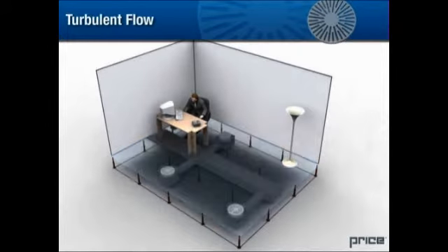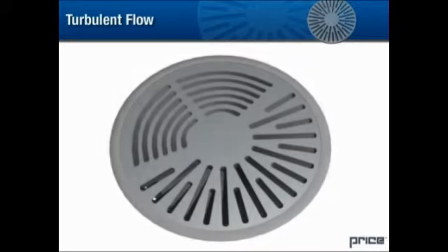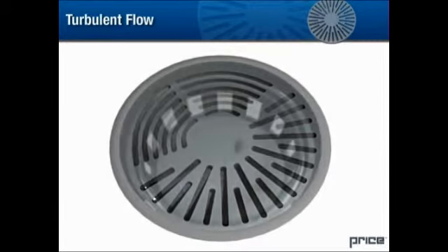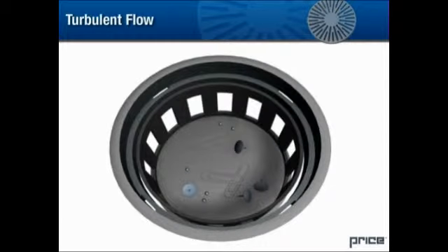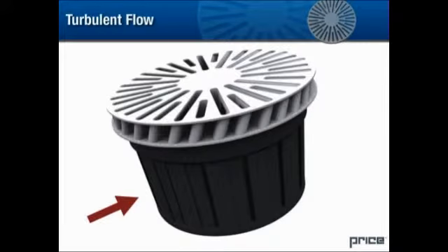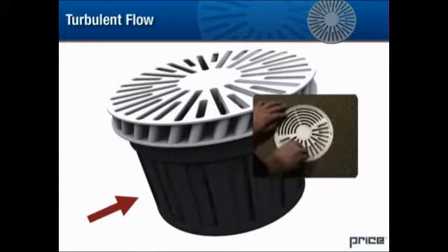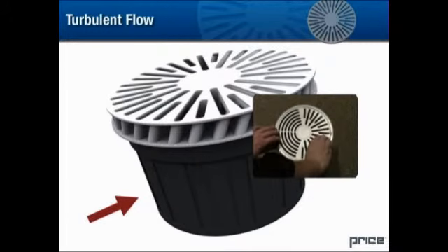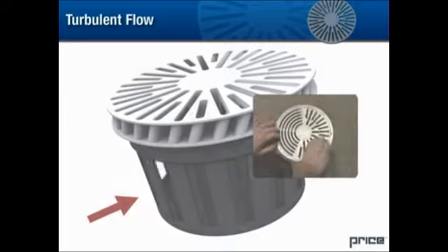The floor swirl outlet is normally inserted in the floor tiles of the conventional raised floor system. A distributor basket may be inserted under the air outlet to trap solid objects such as coins and paper clips that may fall into the air outlets. In addition, some diffusers allow the volume and direction of the local air supply to be controlled by the occupant, allowing their local environment to be individually controlled.